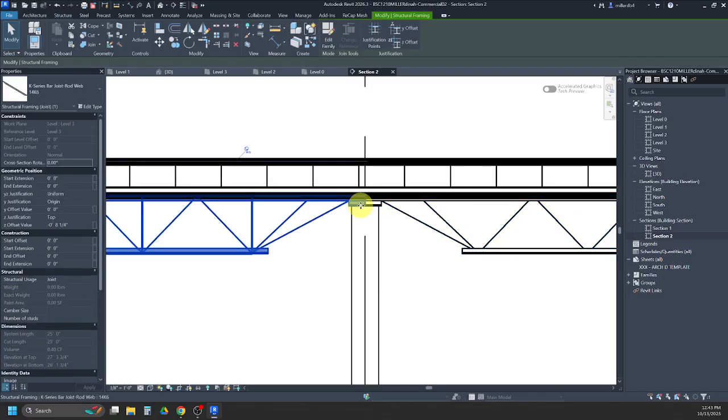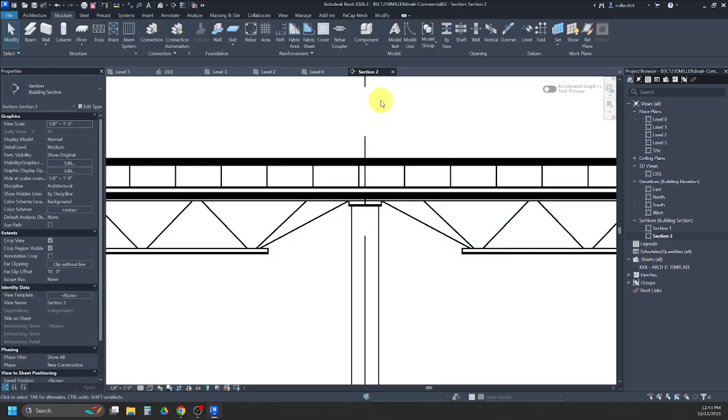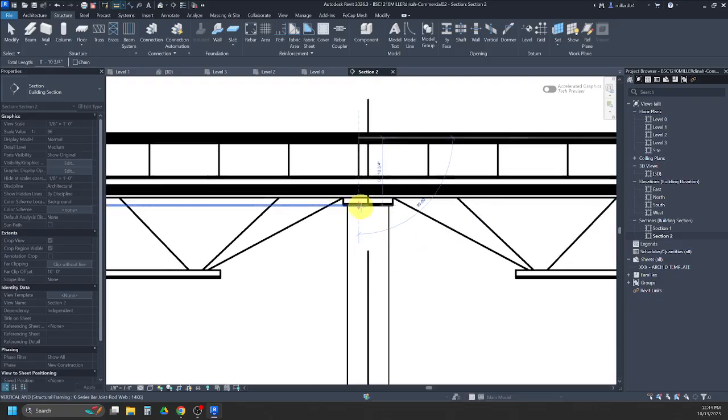I need to figure out what it is from very top to essentially the bottom of this joist here. To do that, I'm just going to use my quick measure tool, which is in your shortcut keys up here, this one with the ruler. I'm going to measure from top straight down, and it's 10.75. So for the beam that I'm going to have run across grid B, I'm going to offset it down -10.75.